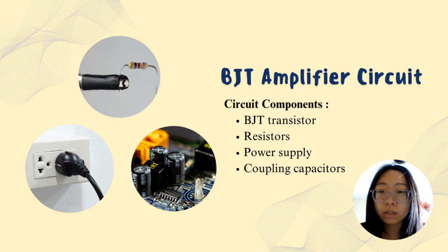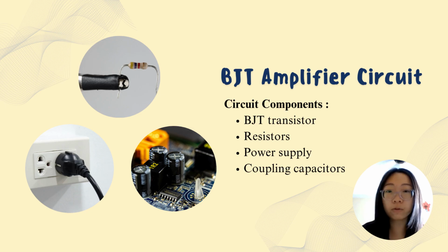In this configuration, a small ECG signal enters the base terminal of the transistor. The transistor then controls a larger collector current, producing a larger output voltage. As a result, the weak ECG signal becomes significantly stronger while retaining its original waveform characteristics. This amplification process is essential because it allows the tiny electrical signals generated by the heart to become large enough for filtering, processing, and also display.